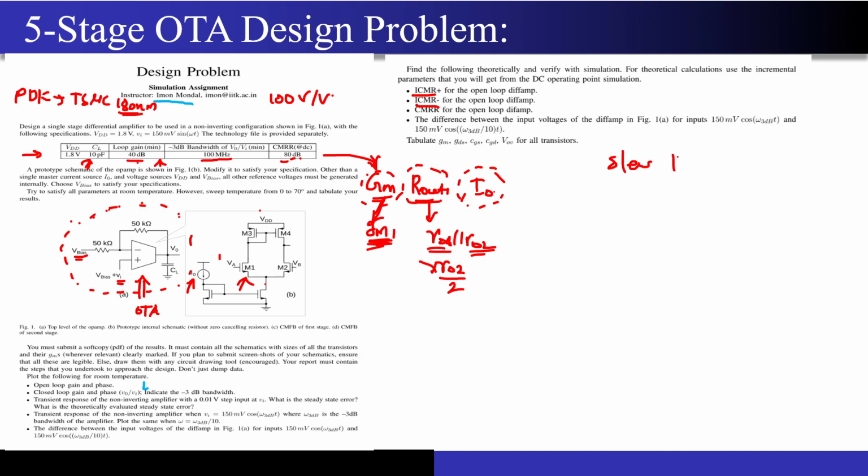I will tell you. The slew rate of the op-amp: if you give a very large signal at the input of the op-amp, how quickly can its output ramp up with respect to its input? So dV0, how quickly the output can change with respect to time, this is what the slew rate is. Then we have already seen ICMR plus, we have already seen ICMR minus.